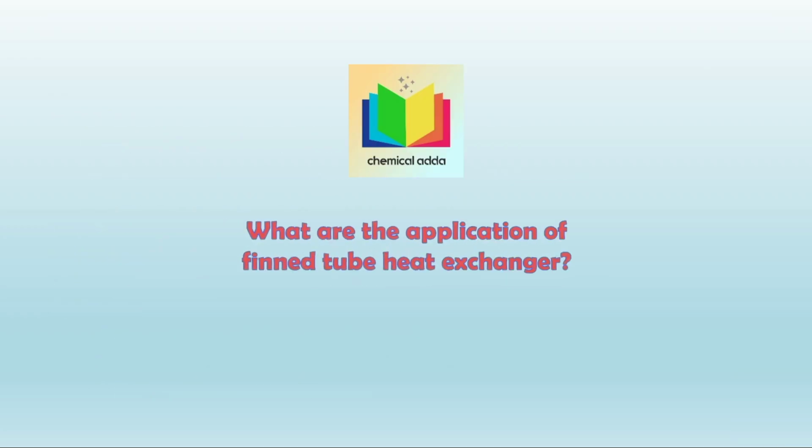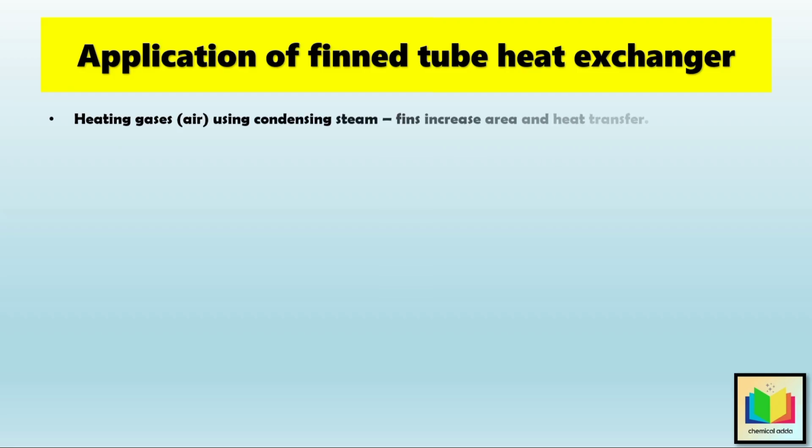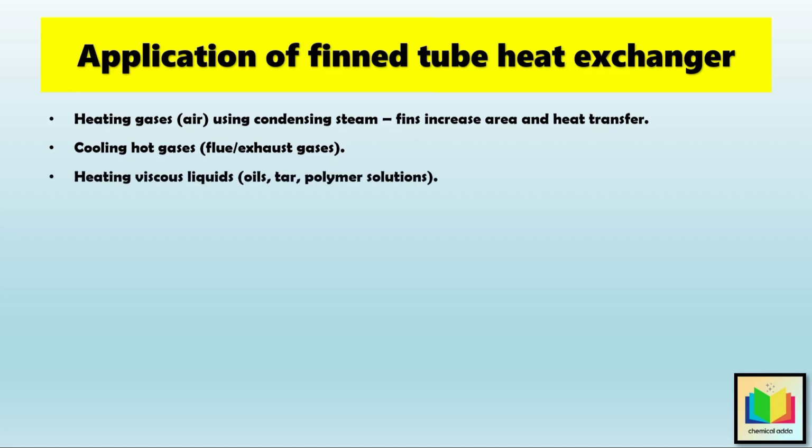Now let's understand, what are the applications of fin tube heat exchangers? First application is, they are widely used for heating gases, like air, using condensing steam. Since gases have a very low heat transfer coefficient, the fins help increase the area and improve heat transfer. Second is, they are used for cooling of hot gases, for example, cooling of flue gases or exhaust gases in process plants. Third is, in the case of viscous liquids such as oils, tar, or polymer solutions, fins play an important role, because these fluids also have poor heat transfer properties.